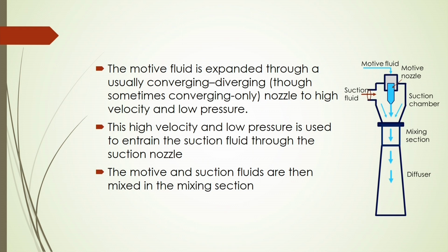This motive fluid is expanded through a usually converging-diverging nozzle, sometimes converging only, to high velocity and low pressure. And that high velocity and low pressure is used to entrain the suction fluid through the suction nozzle, and the motive and suction fluids are then mixed in the mixing section.